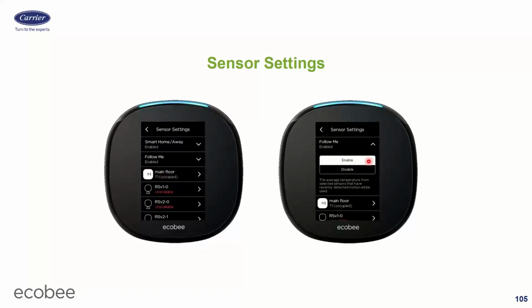The next one below that is Follow Me. You can enable that. If I disable it, then it'll look at all of the sensors and average all the sensor temperatures. If I enable it and turn on the Follow Me feature, it'll only average the sensors in the house that are detecting occupancy. So let's just say you have one thermostat and one sensor. The thermostat's downstairs in the family room, the sensor's upstairs in your bedroom. You're hanging out in the family room watching TV. There's nobody in the bedroom. It'll control to the family room temperature, and it'll completely ignore upstairs. It won't care at all about upstairs in any way whatsoever.